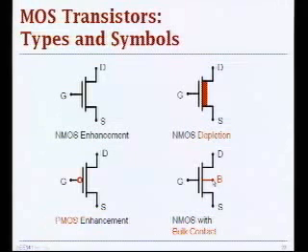Normally your bulk is connected to source, but in some cases you want to have a bias on your body, and this is typically used in analog design more often than in digital, although there are also techniques for body bias in digital design. Sometimes if you want to, for example, put your transistor in a sleep mode, you want to avoid leakage, then you want to do reverse body bias and so on. You can even do forward body bias to improve the speed and various techniques.